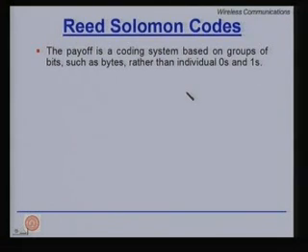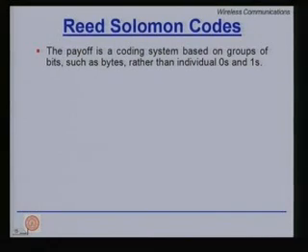So, if we are now talking about symbols and each symbol represents a set of bits, then if we can even make a single symbol error correcting code, then eventually you can correct all the burst errors embedded therein, because correcting one symbol amounts to correcting all the errors within that symbol, but one symbol represents several bits in succession. So, we have actually come up with a very strong burst error correcting code naturally.